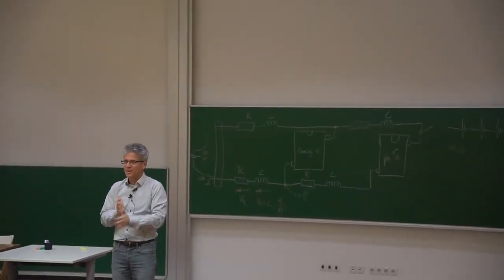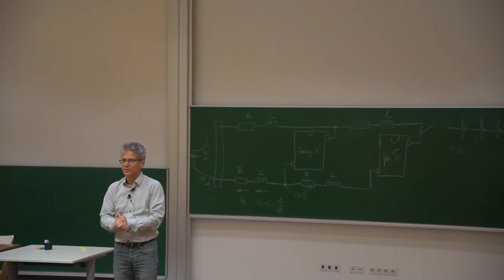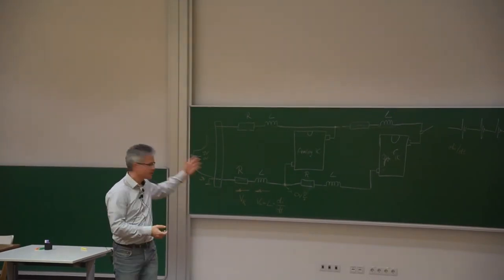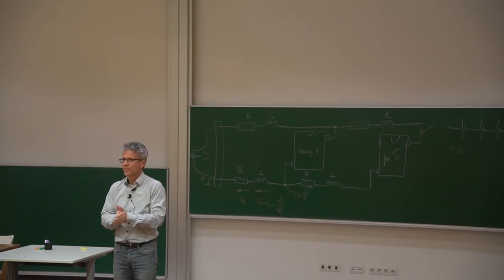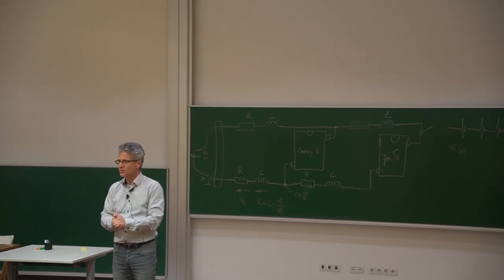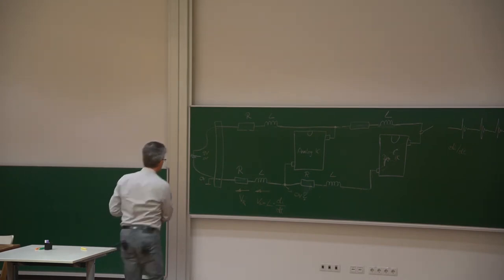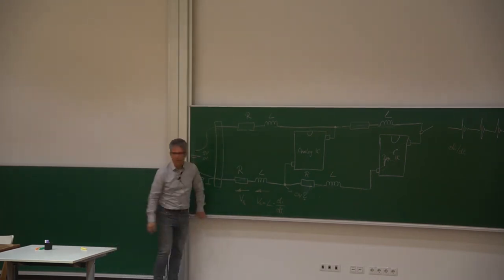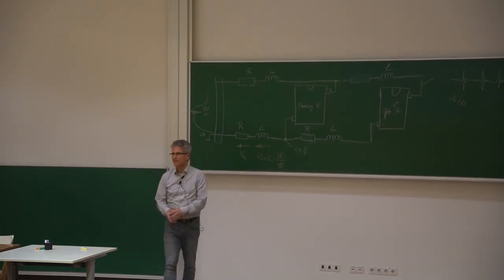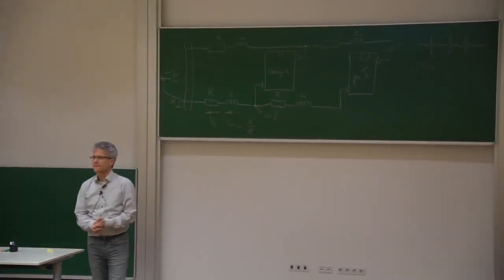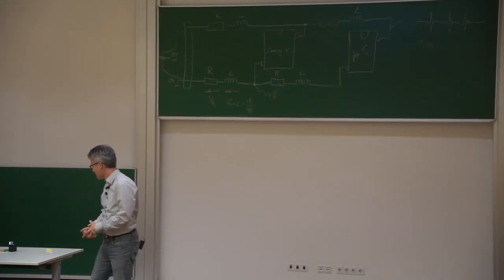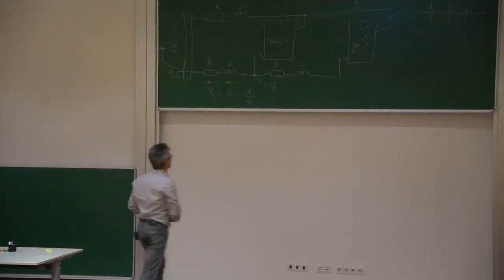Because now comes the important thing: what can we do in order to avoid this EMC problem? I think the generation of the EMC problem is clear, hopefully. But now it's up to you. So let's suppose you're an engineer in a microelectronic company. The customer is complaining that the electromagnetic emission or the coupling or whatever is too big, and it's your job to solve the problem. So what are you doing in order to solve the problem? Use capacitances everywhere. Yeah, there is a reason why I have not drawn capacitors.